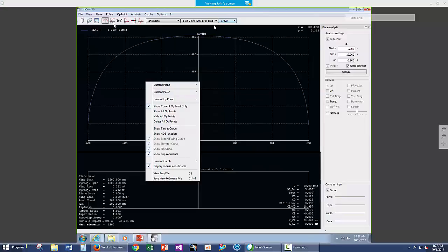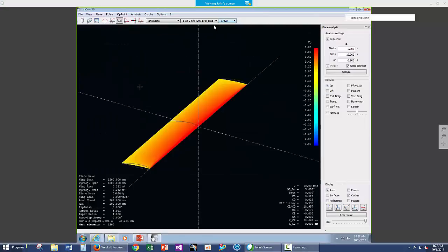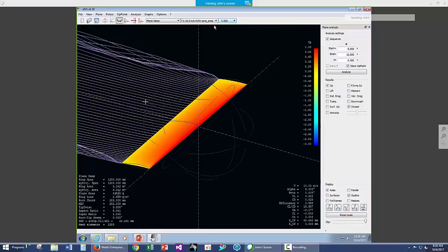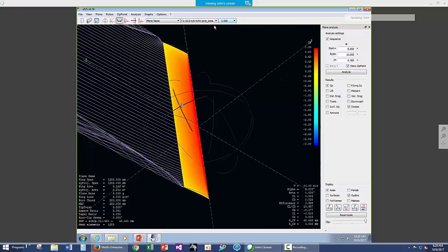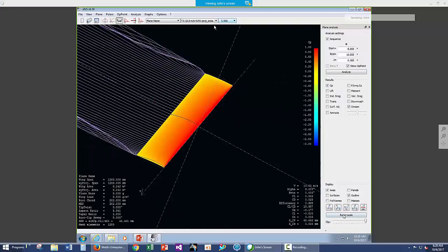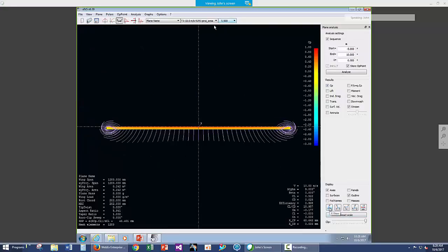Okay. Let's take a look back here. We can also go and take a look at the streamlines. For this case, we can always go and rotate everything around to look at it any way we want to. There's set lines you can see here. You can see the roll-up, the tip vortices. You can see the decrease of the wake in the middle of the wing. This has an effect, of course, on your tail. We'll put it in there.